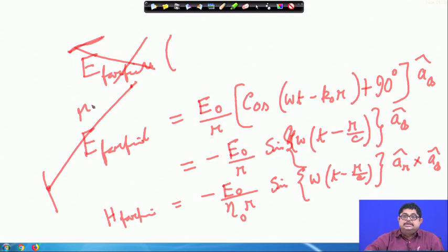They always show a radial flow of power, there is a triplet, locally they are plane waves in the far field, they also have this time delay, they have the space delay according to the wave that created them, e to the power minus j k naught r by r, and they have all these properties. That is why we studied the current element.